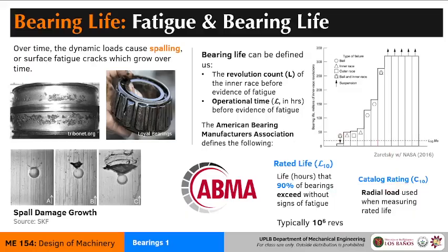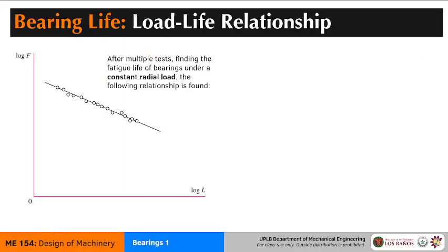Now, this is just one point on the load-life relationship. If you're a manufacturer, let's try out different loads and see how long the bearing lasts. If you do multiple tests, as in hundreds of units subjected to different loadings, you'll develop this kind of relationship.